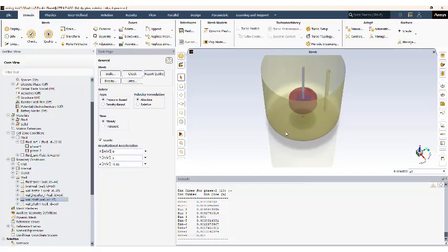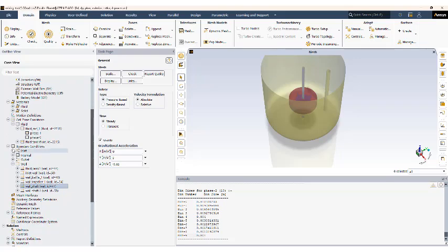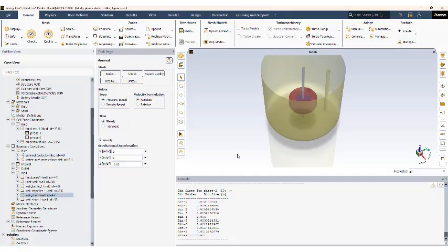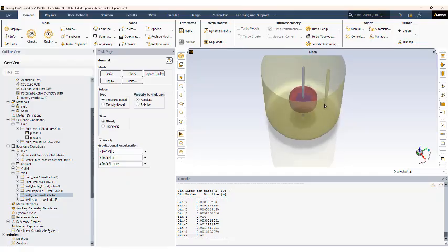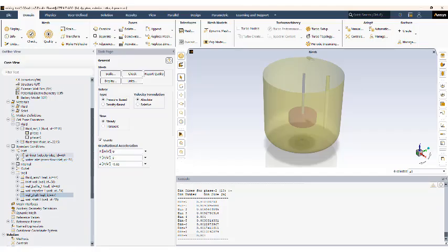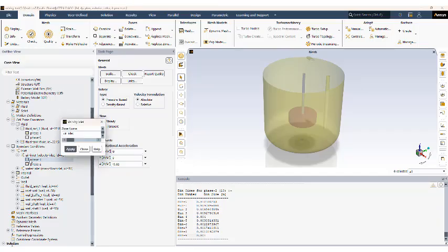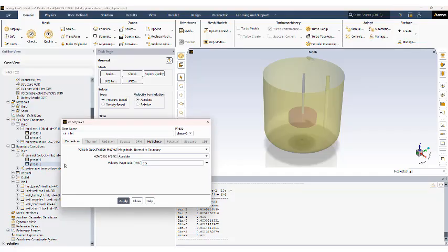So once we've defined all of these parameters, what we need to do now is define the boundary conditions. As I previously mentioned, I have two inlet boundaries. One is for air at this tube here that goes close to the bottom of the tank, and for this I don't have any water flowing, so water is phase 1. Water has a velocity magnitude of 0 here. However, for phase 2 I did specify a velocity of 0.5 meters per second. We can play around with this velocity to see the effects on bubble size and bubble distribution as well.